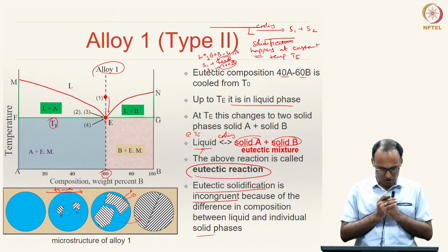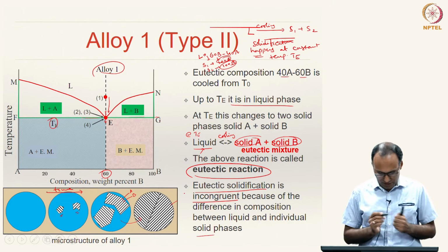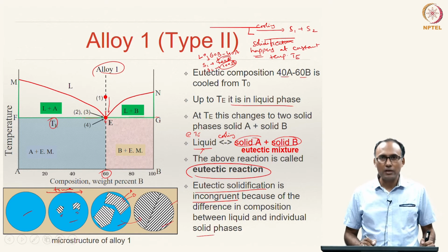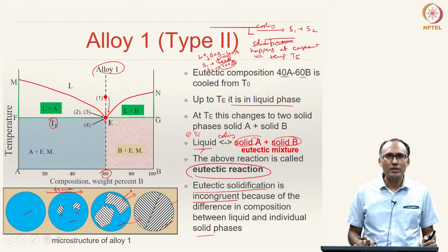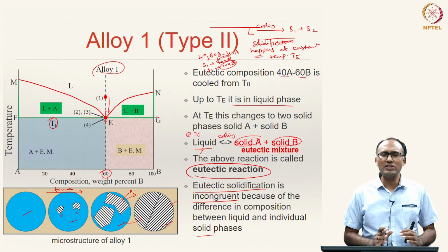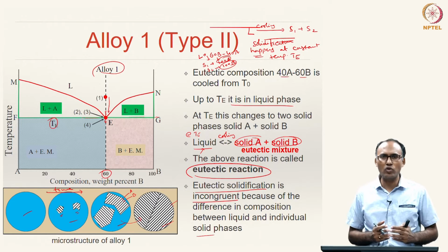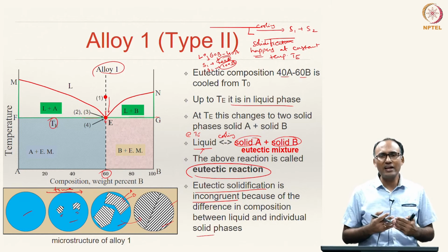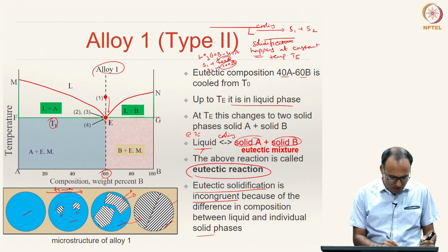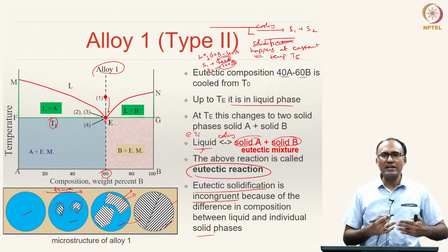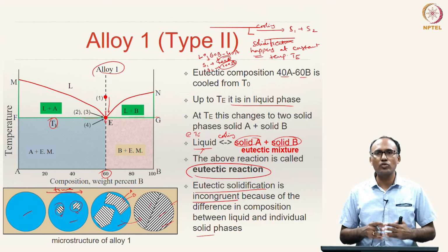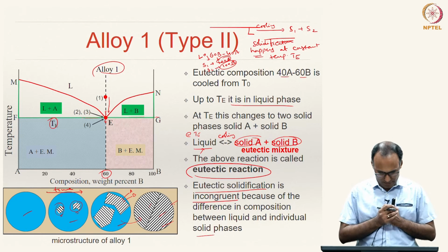It will have this alternate layer microstructure. So, that is what is usually represented here, and please note that the microstructures that we are showing in these 4 graphs are only representative, they are in some sense schematics, they are not the real microstructures. When you see the real microstructures under the microscope, you may have an alternate layer structure looking similar, but not exactly like that. Also, the initial shape of the nuclei or grains can be very different. Here I have only shown 2 grains, it does not mean that in reality also you will have 2 grains, you can have several grains.